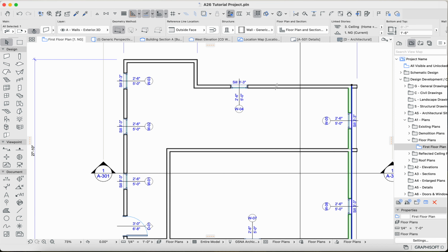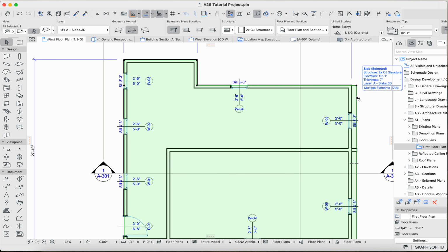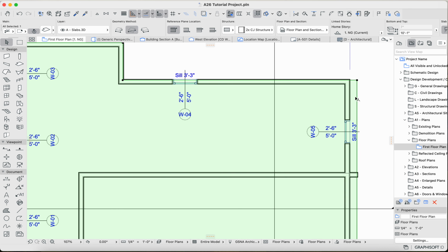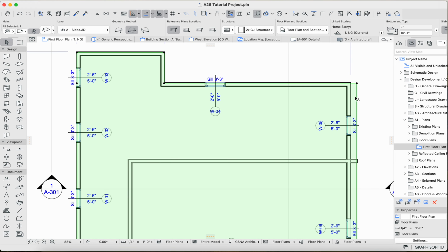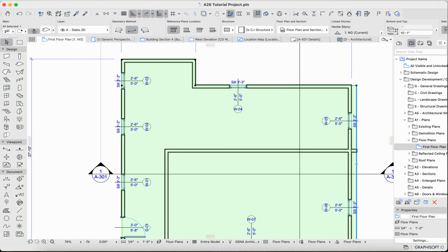I'm going to select this wall here by holding shift and then left clicking, and then I'm going to come up here to the toolbar and intersect. Now we can see that I believe this is either the floor, oh no, this is the ceiling joist structure that we created. This one, since we were using the previous measurement for exterior walls, kind of stayed in place.